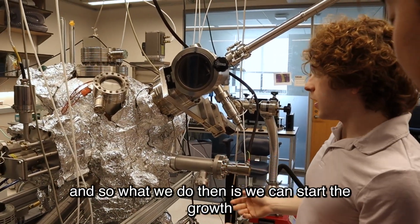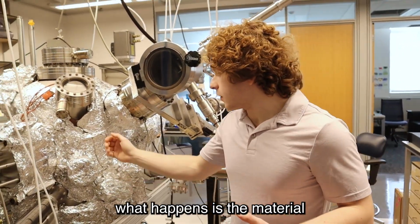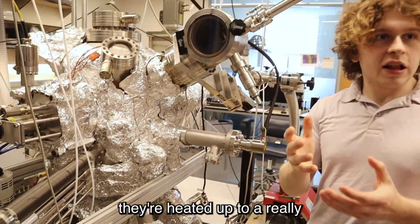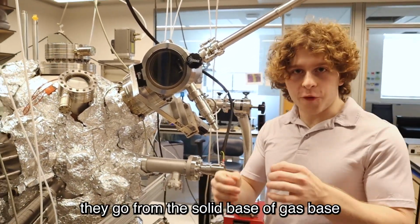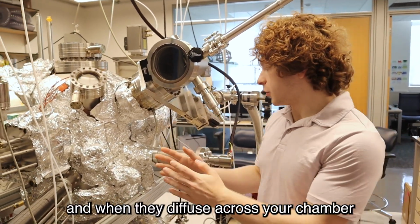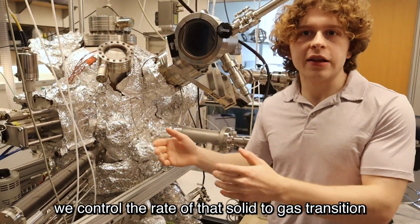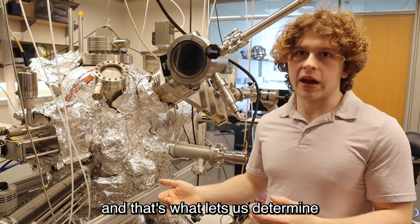And so what we do then is we can start the growth, right? When we start the growth, the material, like I said, is heated up, or the sources are heated up. These are some of the sources. They're heated up to a really, really high temperature, and when they heat up, they go from the solid phase to the gas phase and diffuse across your chamber. When they diffuse across your chamber, they can hit on top of your sample and plate onto your sample. And so by controlling the temperature, we control the rate of that solid to gas transition, and that's what lets us determine how much we're growing.